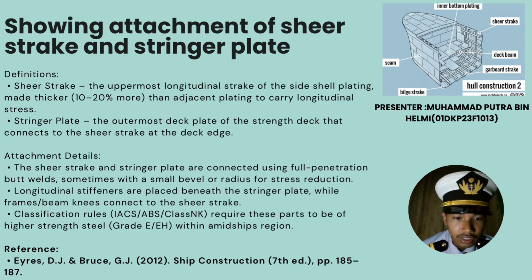For the conclusion, the sheer strake and stringer plate form one of the most important connections in ship construction. The use of thicker plates, full penetration welds, stiffeners, and high-strength steel ensures the safety and durability of the vessel.